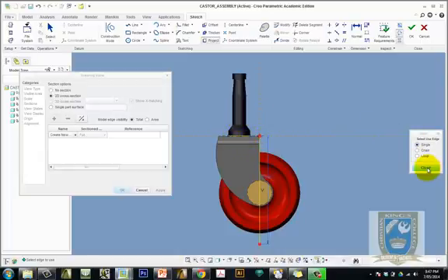Close the project tool. This time go back to my line, and as I move my cursor along that line, the M pops up, meaning midpoint. That means I've got it directly in the center. So click once for midpoint, drag it up vertically, center mouse button to finish.